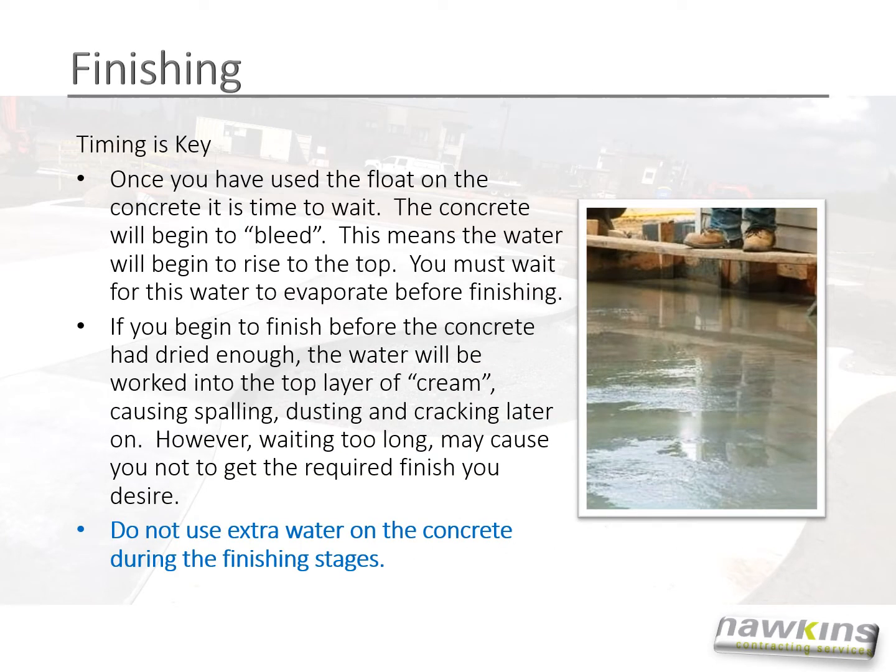Finishing. Timing is key. Once you have used the float on the concrete, it is time to wait. The concrete will begin to bleed. This means the water will begin to rise to the top. You must wait for this water to evaporate before finishing. If you begin to finish before the concrete has dried enough, the water will be worked into the top layer of cream, causing spalling, dusting, and cracking later on. However, waiting too long may cause you not to get the required finish you desire. Do not use extra water on the concrete during the finishing stages.